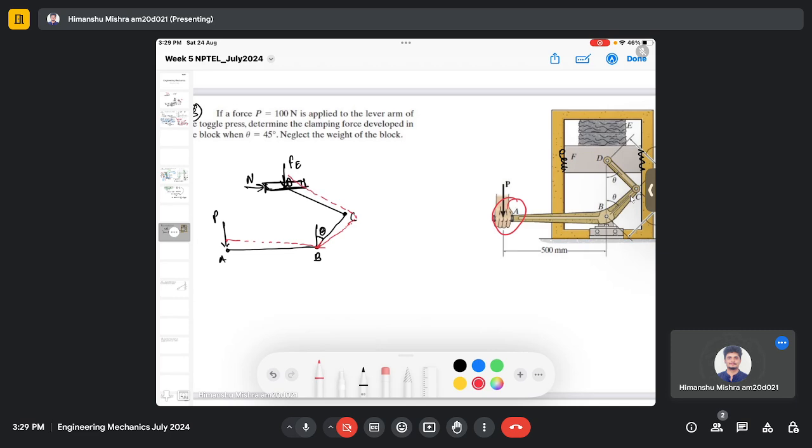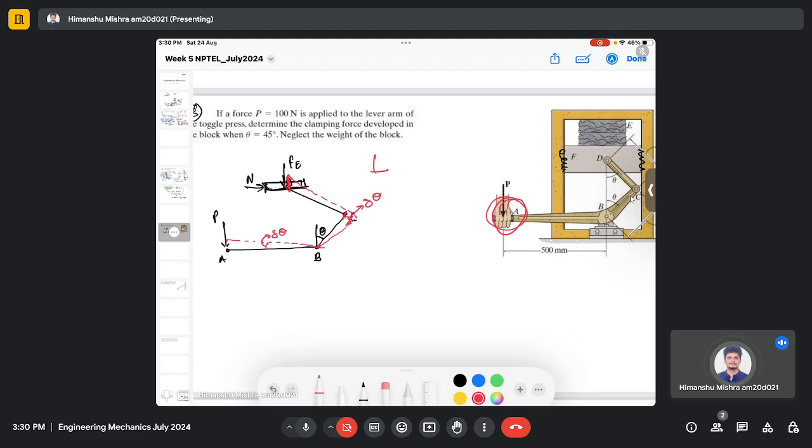Okay. So due to this virtual displacement, let's say it's del theta. Here also this is del theta, because it's the same angular displacement exerted due to this force P, and there is a displacement along force Fe.